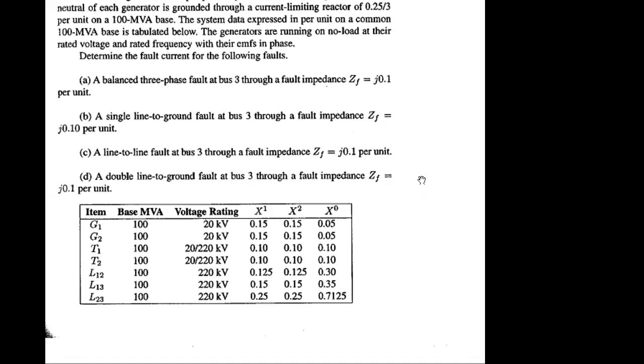Could you kindly, Tasin, summarize in 2 lines what we have to do? First of all, if this is the scenario, or if you have been given any single line diagram, can you address the fault current? Yes, you have to just start with Thevenin. First, you have to find the Z equivalent using the Thevenin equivalence theorem for 3 different scenarios.